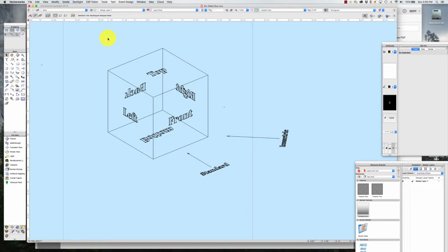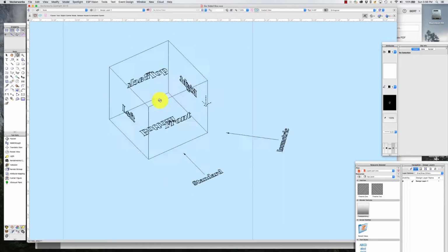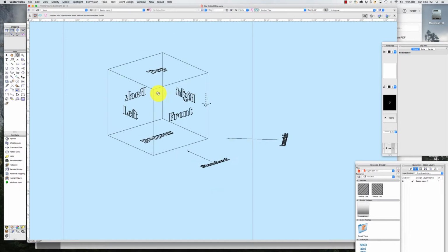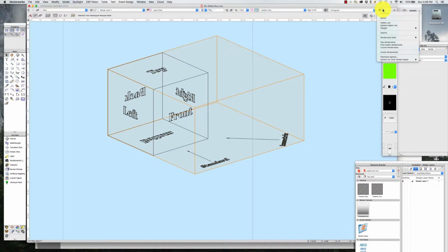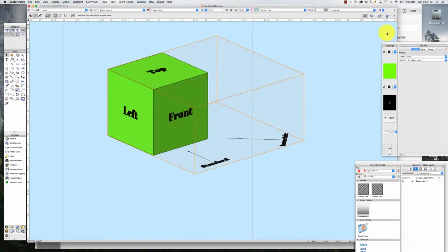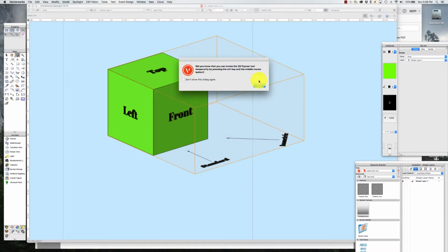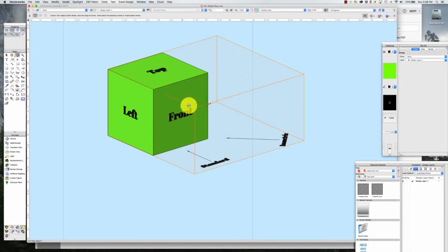It can be a little bit confusing, but it is the fastest mode. So if you're working on a really complicated model, spending a lot of time rotating around it or looking at it, and it's taking a long time to redraw, wireframe is the fastest mode. The next fastest mode is OpenGL. This is a rendering mode where everything is filled in, but it's not really photorealistic.